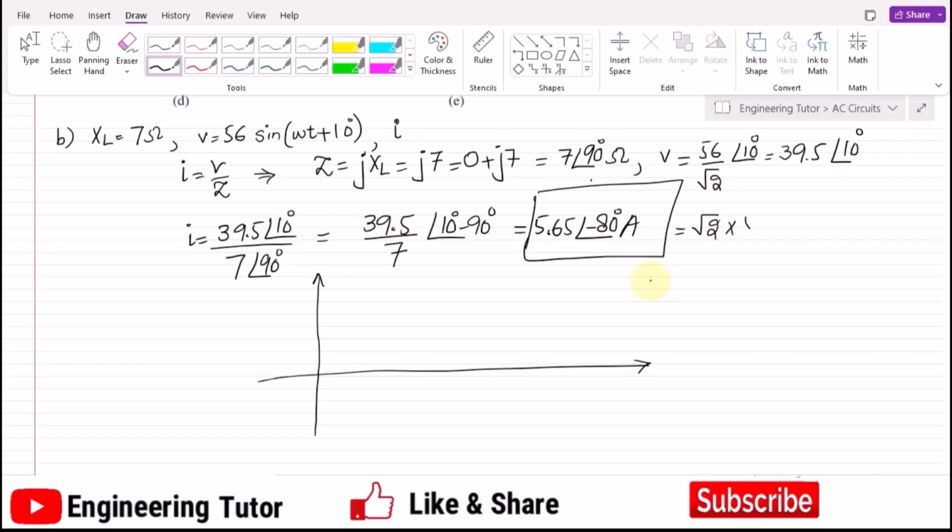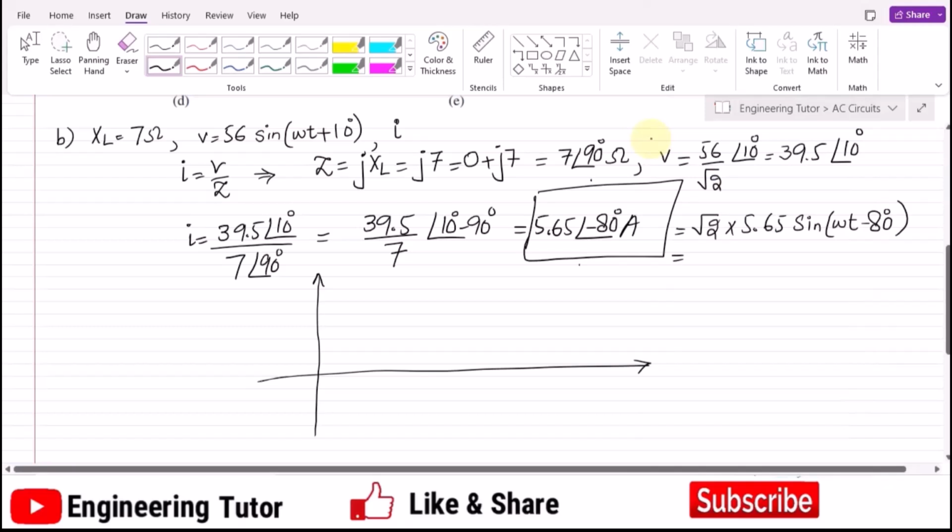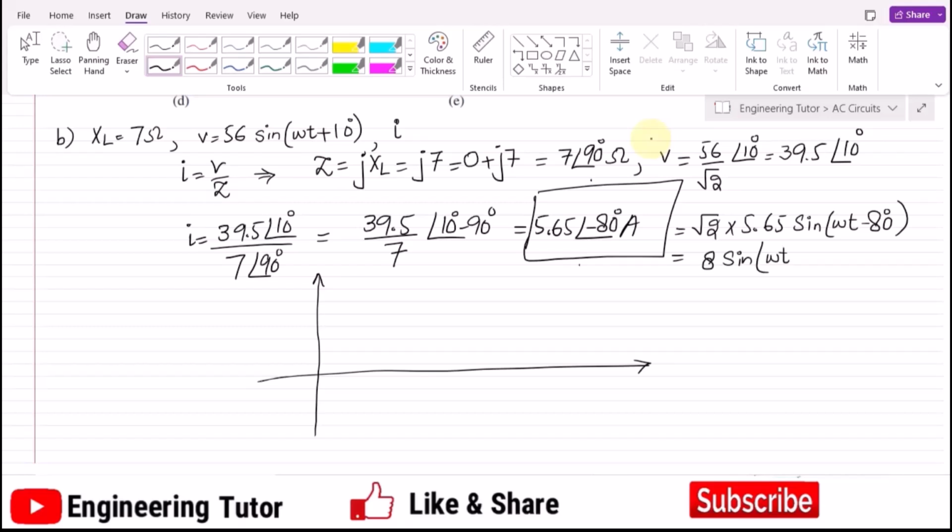So that would be 5.65 sine of omega t, with angle minus 80 degrees. 5.65 multiplied by square root of 2 will be 8. So 8 sine of omega t minus 80 degrees. That is for the current which is flowing through our inductive reactance.